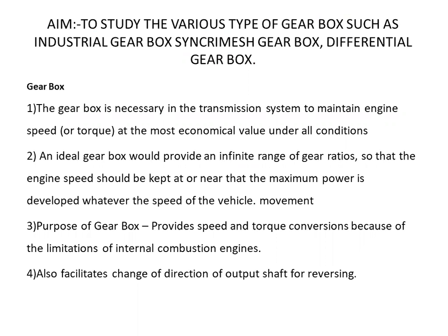And then what are gearboxes? The gearbox is necessary in the transmission system to maintain the engine speed at the most economical value under all conditions. An ideal gearbox would provide an infinite range of gear ratios so that the engine speed can be kept at or near the point where maximum power is developed, whatever the speed of the vehicle.